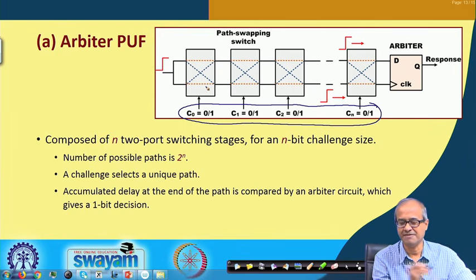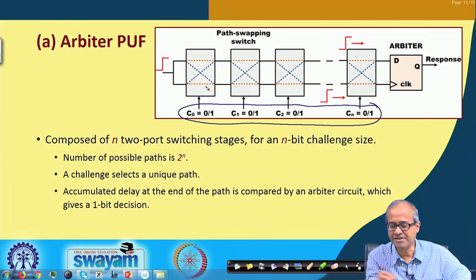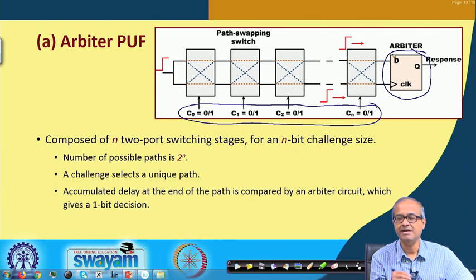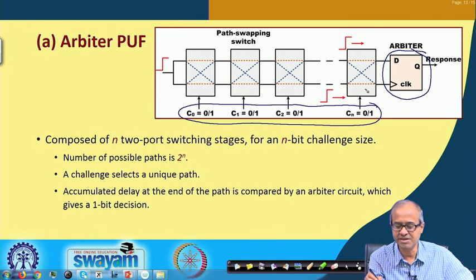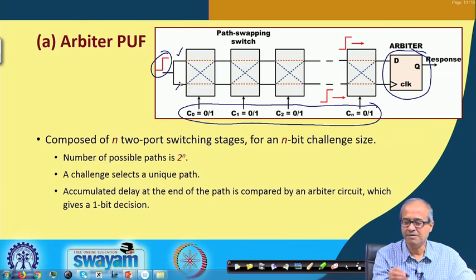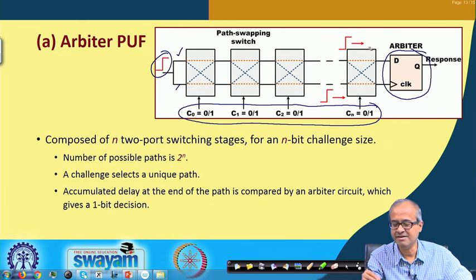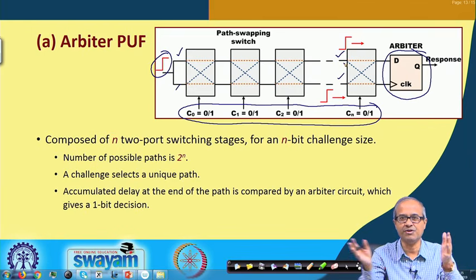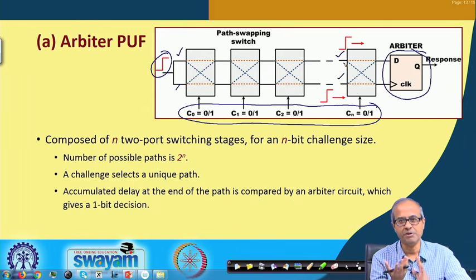So, the delays are different. So, when it reaches a final D flip flop, the delay can vary, that means which input will reach first. Here you see the same signal was fed to both of the inputs, but when it reaches here the two inputs may be different, may be a little delayed with respect to each other, because they are following two different paths, the two paths are not identical.